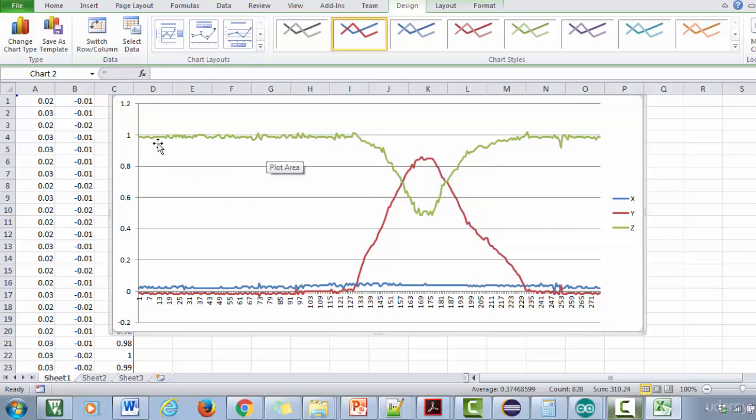And look at Z here. The Z value actually decreased, right? Because of that tilting operation on the Y axis, you can see that as the G value of the Y started increasing, the G value of the Z axis started diminishing. It's because the force of acceleration due to gravity is now shared by these 2 axes, right? Right now both the axes are experiencing the force. So that's why the value is divided across the Z and Y axis, as shown in this diagram here.